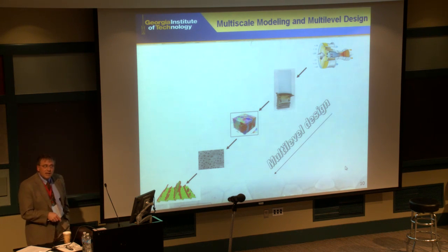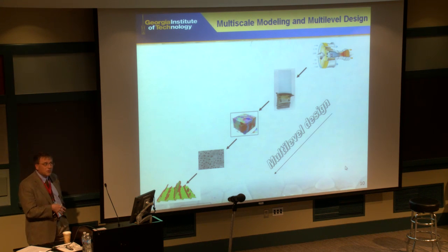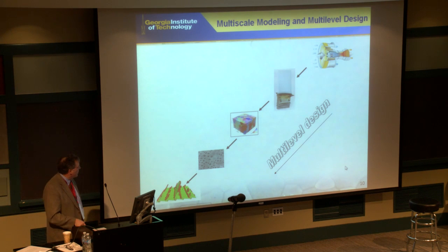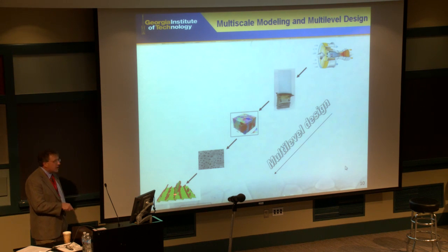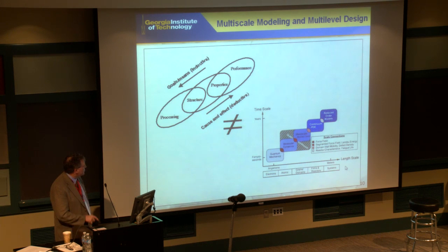But as we see, multi-level design of a hierarchical system has to do with the information flow between these levels of hierarchy, right? In the case of nickel-based superalloys, you've got a blade. If it's a polycrystalline blade, here's the polycrystal rendition with grains on the order of a few microns to tens of microns. These are precipitates that may range from 30 nanometers for small tertiaries up to the order of a micron for primaries. And then, of course, you have dislocation interaction with interfaces. It's very discrete and occurs on length scales that can be amenable to atomistic description.